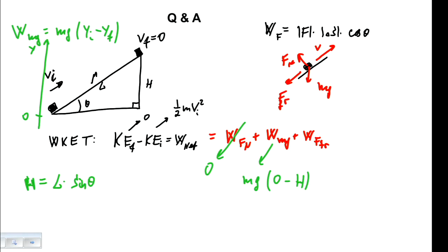And friction. Well, for the friction, we know that the angle always equals 180. So it gives a minus. And friction equals coefficient times normal force, and that's supposed to be times distance traveled. So what should we write for the friction? A minus, a coefficient. I'm going to move the distance over here.